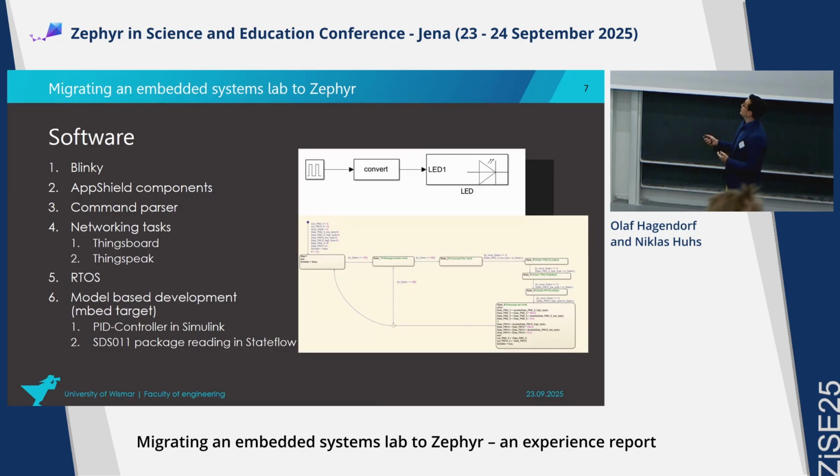So here you can see on top, basically just a Blinky in Simulink. So we have a PWM, a converter block for the right data type, and then the LED of the microcontroller as a fixed block in Simulink.